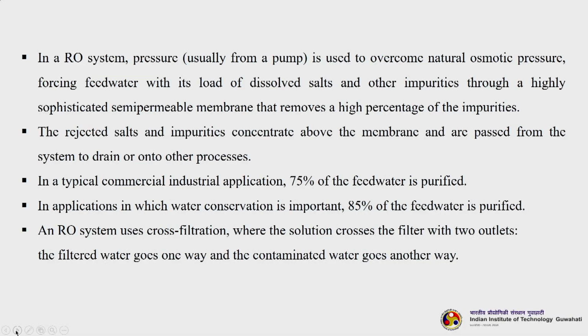Immediately they will foul, so biofouling is a problem. Apart from that, there are other smaller and higher molecular weight salts also. It is not only sodium chloride. All these things need to be taken into consideration when designing an RO membrane for desalination purposes. The rejected salts and impurities concentrate above the membrane and are passed from the system to drain or onto other processes.